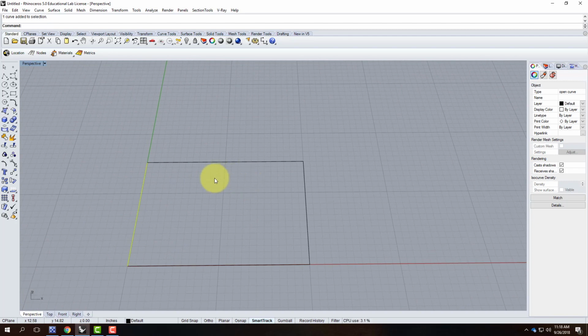And the first thing that I want to do is I want to kind of soften the edges of this curve a little bit. And I want to make it so that all of these sides aren't perfectly straight. And so to do that, I'm going to actually control the line, or the curve, with its control points. And to see those points, I can type the command points on, or I could come over here and click this button for points on and points off.